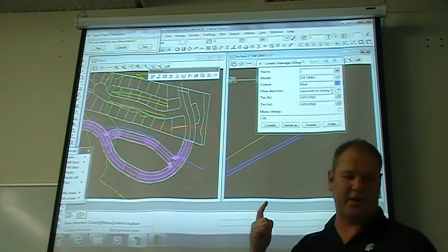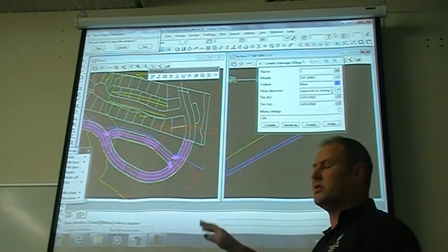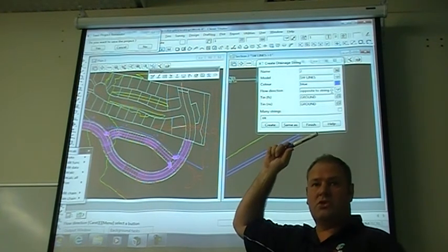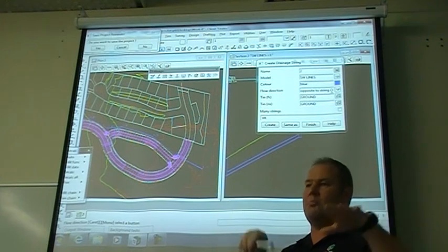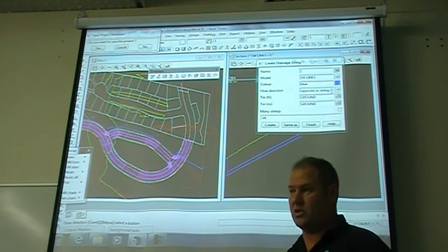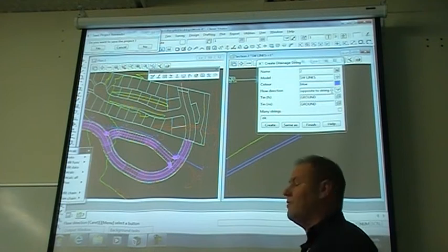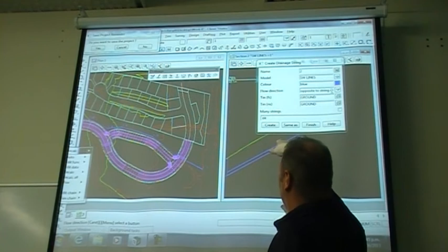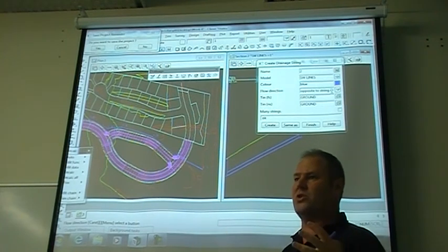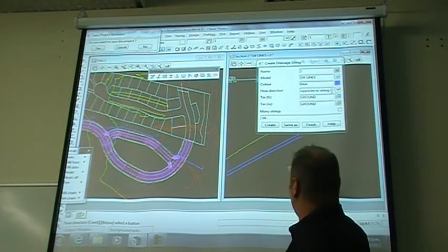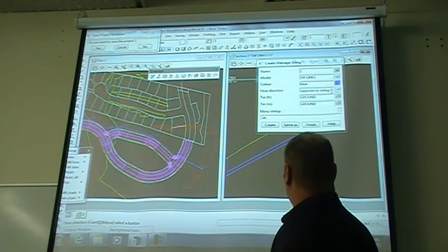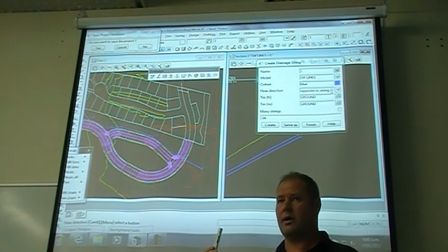Now I've only got one tin in here, it's just the default data set that I've given you. We need a finished surface to design to, so that as we place these manholes, it's going to adopt the point on the ground as its lid level. So tin FS obviously is finished surface. If we had a flash design tin, that's the one we'd select. In this case, they're both the same data set. Okay, so we've got to have a tin nominated under finished surface. Clear as mud?